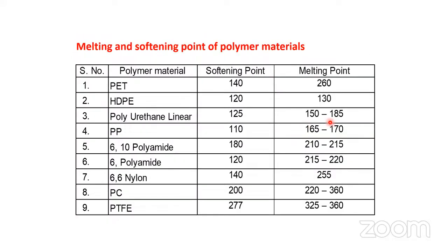If you see here, for many of the polymeric systems, a range of melting point has been mentioned. It starts melting and continues until it is completely in molten form. We can't say it is in a liquid form, we can say molten form. The complete material should become molten, and until that time it is heating. Which value do we take as the melting point, the start or the end? This is generally a range. We can't say only one.